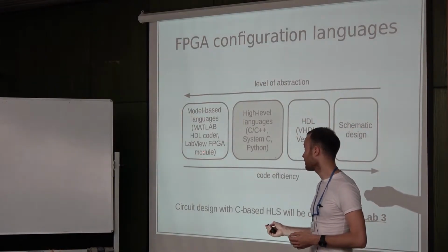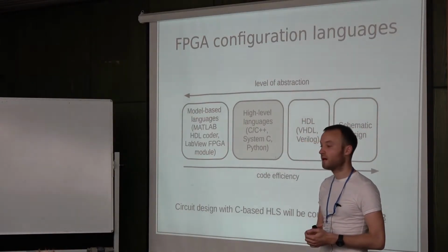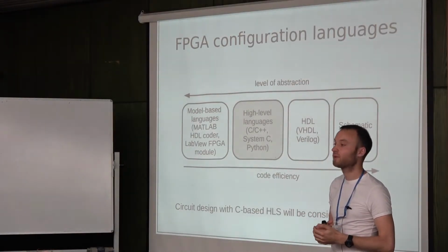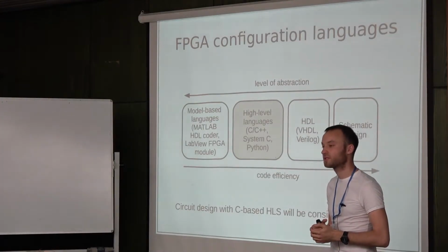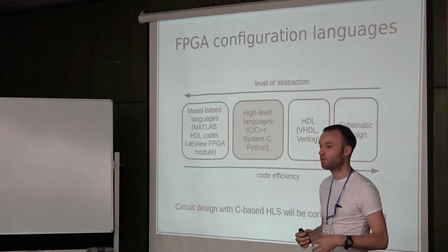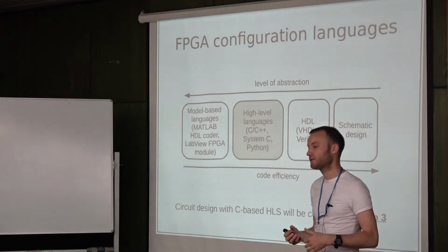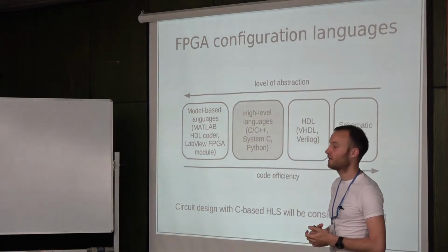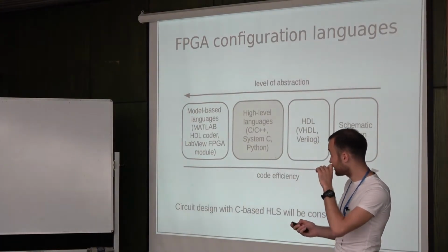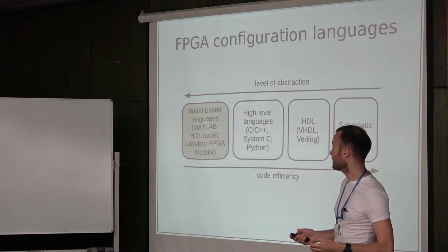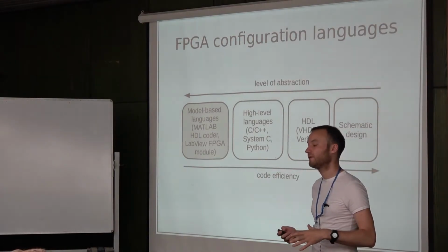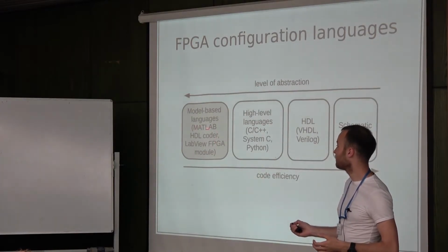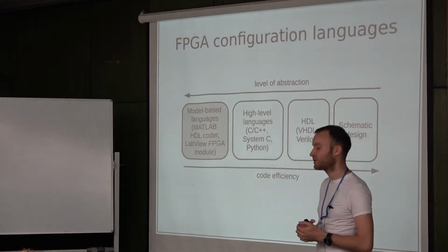And the highest level approach is using model-based languages. I think the most popular example would be National Instruments with their LabVIEW FPGA module. They provide you both software and hardware. Although their hardware is also based on Xilinx tools, they provide a nice wrapper so that you can use FPGA from a high-level environment, LabVIEW. The same applies for MathWorks with the MATLAB HDL Coder.